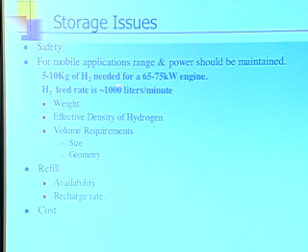The other thing that's very important, a lesson learned with the full electric battery vehicles, is you need range. If you've got to fill up your tank every 50 miles or so, that's not good. The magic number is apparently 300 miles. We expect to go about 300 miles between fill-ups, otherwise it's unacceptable. So if you factor all that in, you need to carry somewhere between 5 and 10 kilograms of hydrogen on board to get the kind of performance and range you're interested in. We need to be able to do that without adding excessive weight to the vehicle, obviously.